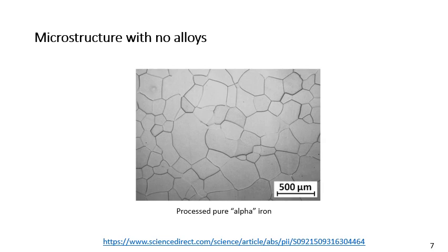Since this class is about microstructure, let's pause again here to talk about what the microstructure would look like if we made our line pipe out of the product at this point. After the basic oxygen furnace, we've removed almost all the other elements other than iron. So there's no alloying elements, no solid solution strengthening like that would come from elements like manganese or silicon. There's no second phase that would come from the iron carbide, the pearlite. What we're seeing here is almost pure iron in the ferrite phase with very large grains.